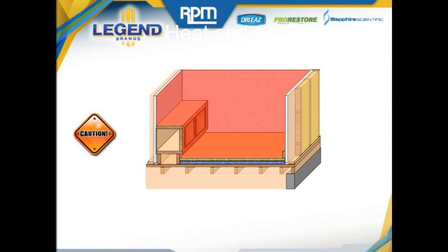In this image of a basic structure, we can see how heat application will not be universal throughout the drying project. Represented in red is the highest temperature air influenced by the direct addition of heat to a space. However, as that air comes into contact with building materials, the heat resistance value of those materials will prevent even energy transfer. In all of the neighboring spaces represented in orange, we see spaces where a cooler temperature will exist. Water vapor in the area in red generated by drying and evaporation will move into these spaces.